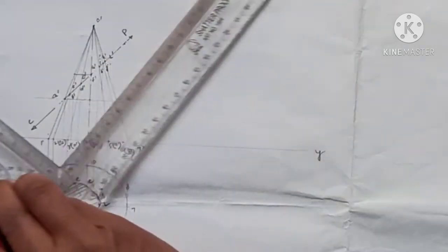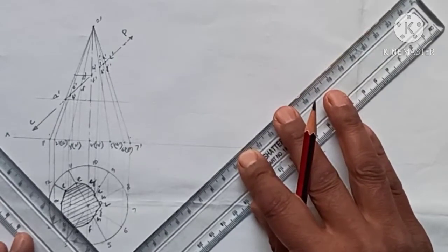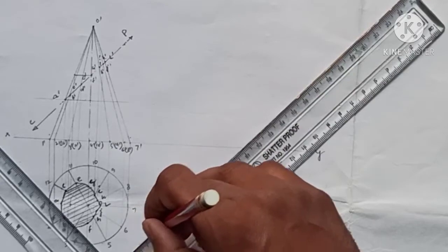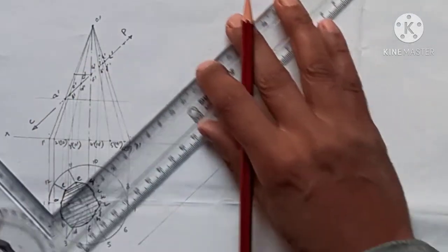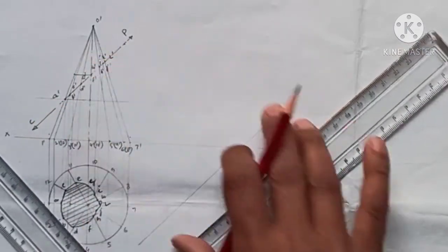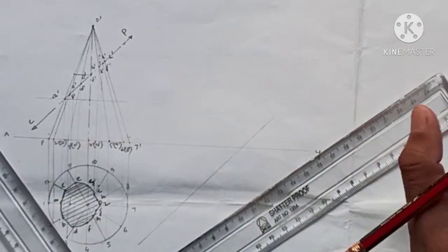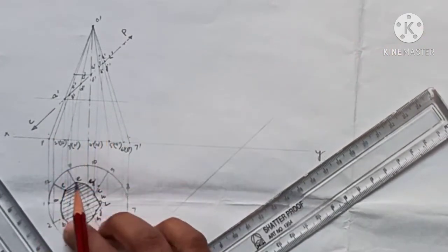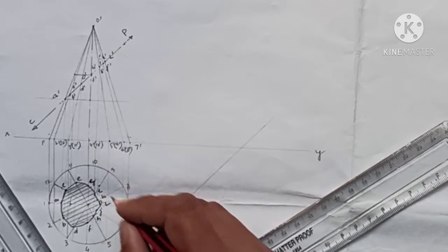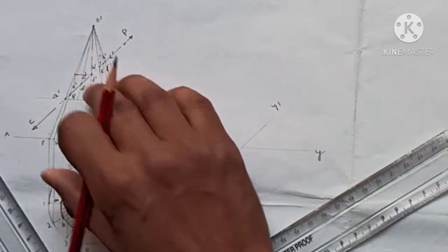For the true shape, what I need to do, I will draw a line parallel to this line. So I will draw a line which is exactly parallel to this cutting plane. I have taken a line, and that line is exactly parallel to this cutting plane at any distance, at any location. It doesn't matter, you can go up, you can go this way, it doesn't matter. Fine, we have to draw the true shape of this truncation. So we can name this, this is my x1 and y1 line which I have drawn parallel to the cutting plane.